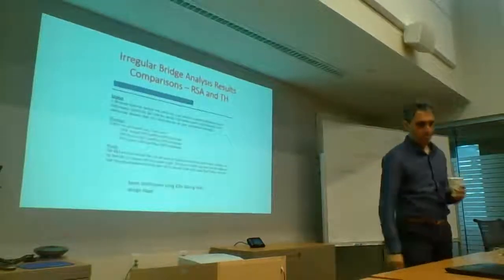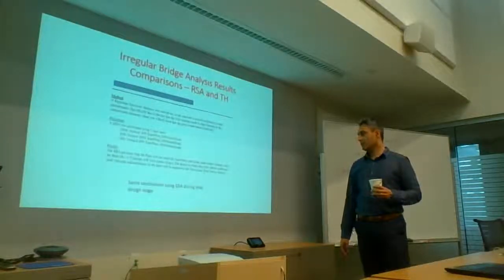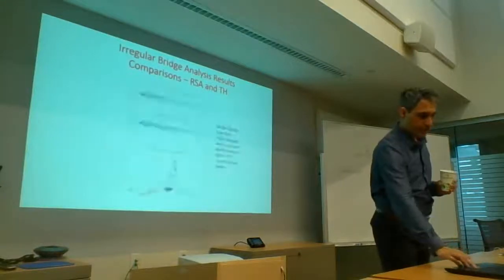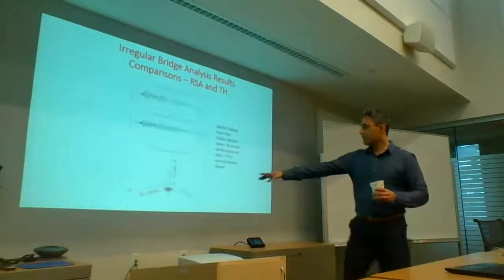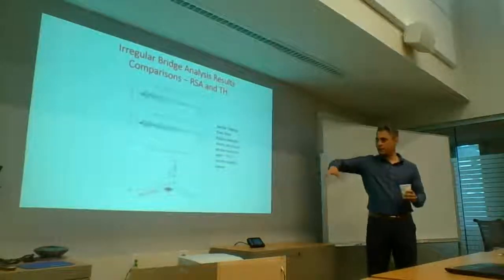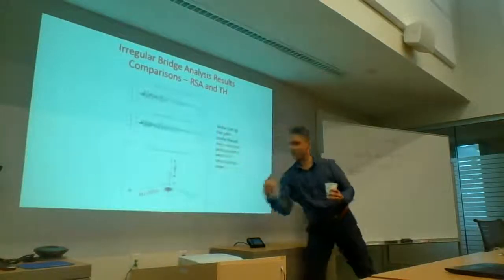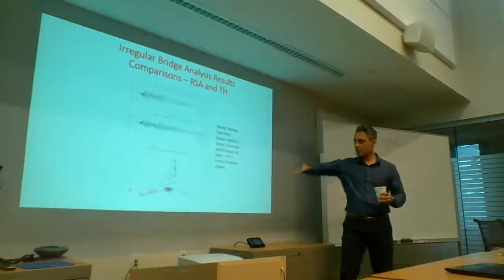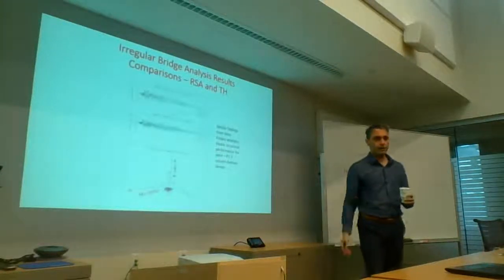So now we got the project. After we got the project, we ran it again. We got the same conclusions at that point. We ran the time history analysis, P13. So this is a PM, X, and Y curve that's plotted in 3 dimensions. And within this, there's that trace of the PM demands. You can see that as long as it doesn't touch the cylinder anywhere, you're meeting the performance.